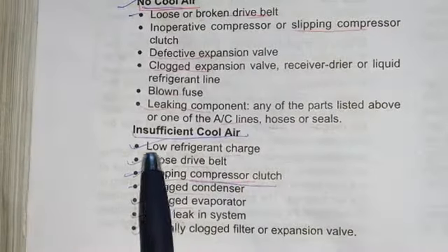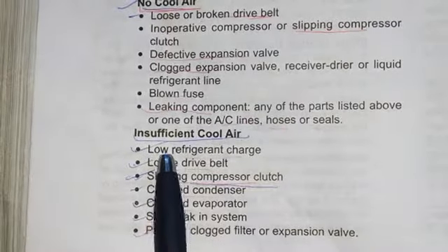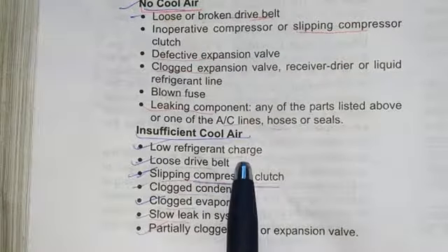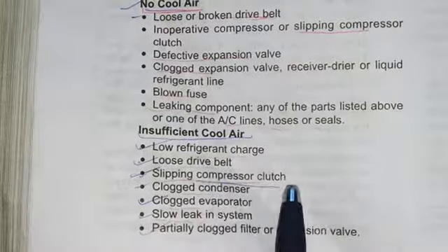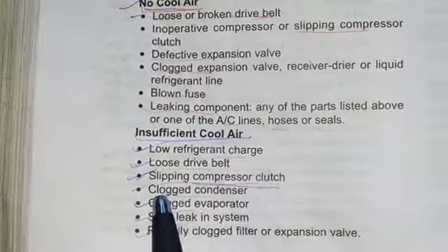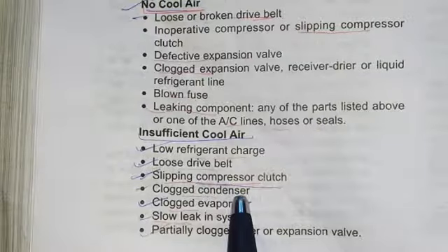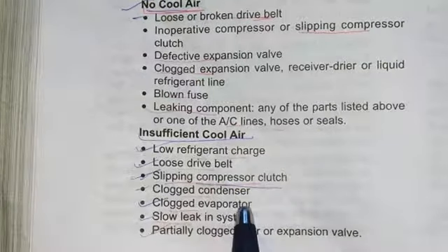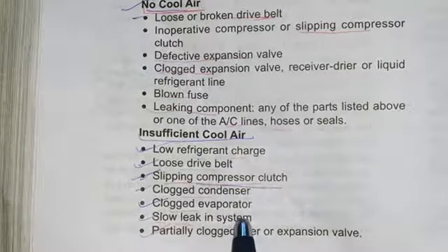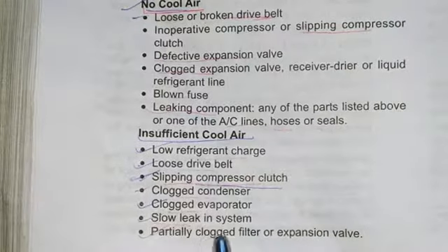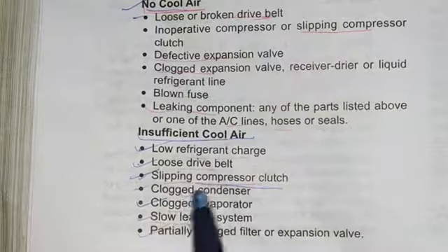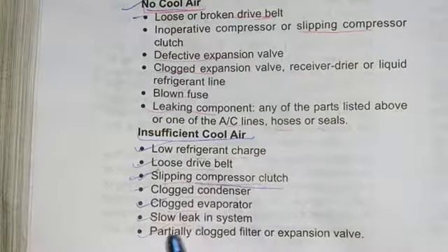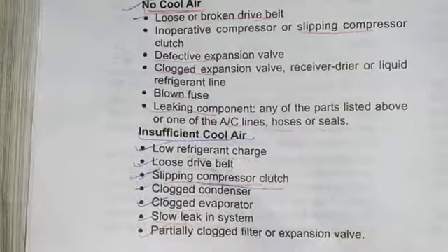Insufficient cool air is due to low refrigerant charge, loose drive belt, slipping compressor clutch, closed condenser, closed evaporator, slow leaking system, partially closed filter or expansion valve. So this closing problem can be solved by cleaning the condenser, evaporator or filter, dryer, expansion valve.